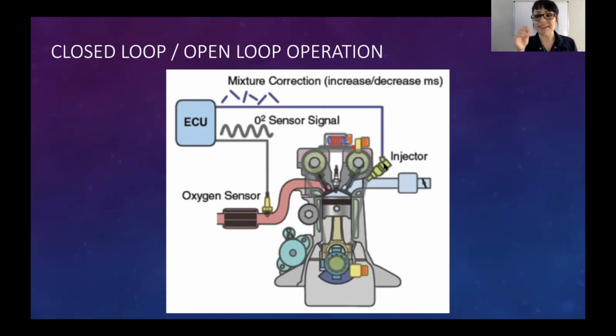Oh, sorry, let me go back here. There are some sensors not involved in this picture, but let's say the ECU sees 50% throttle, it sees this many grams per second of air, and it sees the engine coolant temperature sensor. It sees those inputs and it says, okay, this is how much fuel I think we need. It will command the fuel injector to spray for a certain number of milliseconds in pulse width, right? And then it's going to put air and fuel inside of our cylinder.